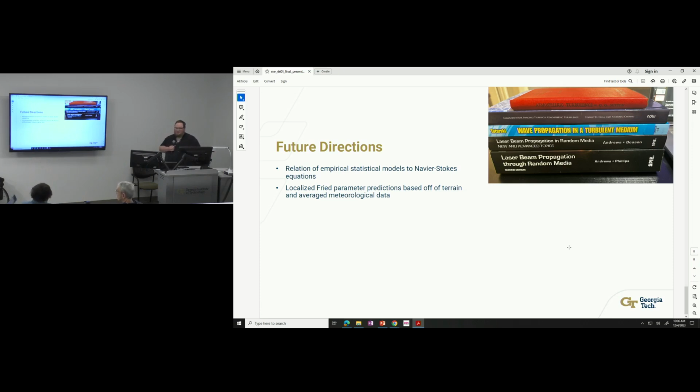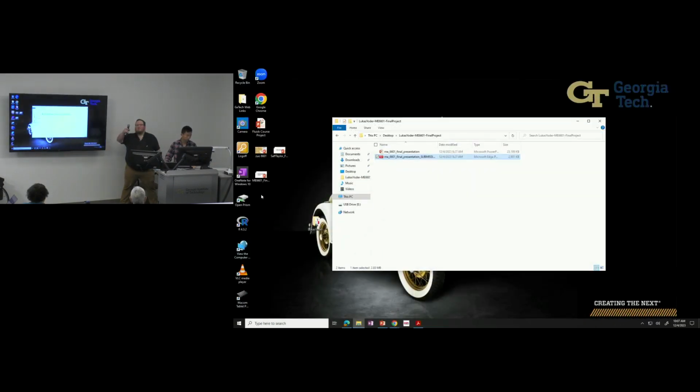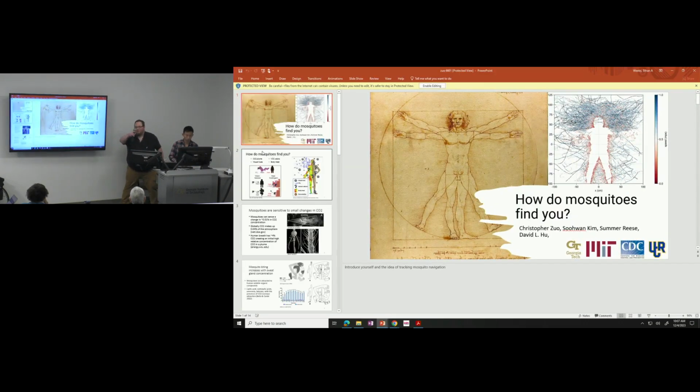I'm not so familiar with turbulent flow regimes, but is it possible to have a steady state turbulent flow, or are the eddies always transient in time? So even with the simulation that I performed, as we advance in time steps, the eddies move to the right of that image. As an eddy reaches a critical size, it moves to the right, and then another eddy is formed off of that edge of the cliff, closer to the cliff, that then reaches another critical size and then moves along in that path. So those eddies don't stay in one location.